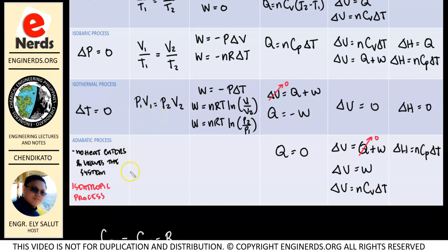But this is actually also the same as saying that our process is operating as a reversible adiabatic process. And if we are operating at reversible adiabatic process, our work can also be calculated as nR times T2 minus T1 over k minus 1. So this is applicable if we are working in non-isothermal condition, no?